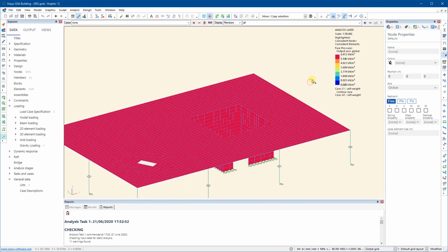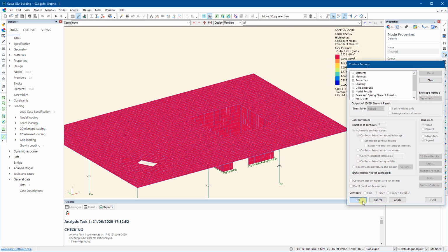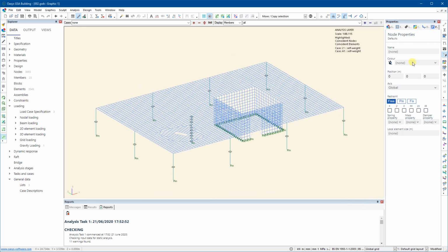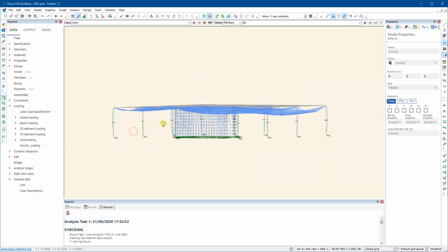So it's a way of checking that the load has been applied, and also applied to the members we think it's been applied to. So if I clear that, we get back to the model. Just to look at the deflected shape again, a quick check of the deflected shapes often tells us whether the model's working as we expect. That's the deformed image button that I'm pointing to on the top right. If I click on that, you can see the deformed shape.